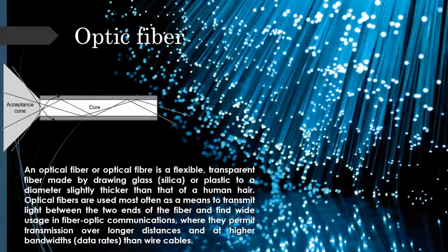Now let's discuss a little bit more about optical fibers. It is different from the rectangular waveguides because it isn't hollow, but has a core of silica glass surrounded by a transparent cladding of material of lower refractive index. Because of this, total internal reflection occurs repeatedly inside the core and the signal travels forward.